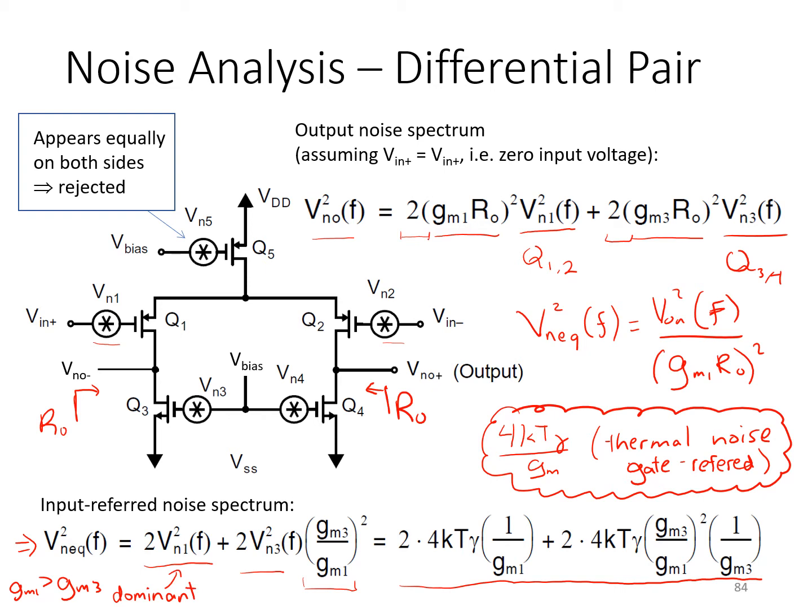That is, that the input pair transistors have a larger small signal transconductance than the active load. Now, we're probably motivated to ensure that the input pair transistors have the largest possible small signal transconductance gm for a given bias current, because that gm1 is also related to the unity gain bandwidth of the op amp and other things that may be desirable, its gain.